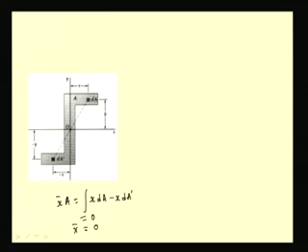And similarly, if we take the other integral, that is y bar A equal to integral y dA, we again see that for each of this element we have the complementary element dA prime, and this quantity is 0, and thus we find y bar is also 0.